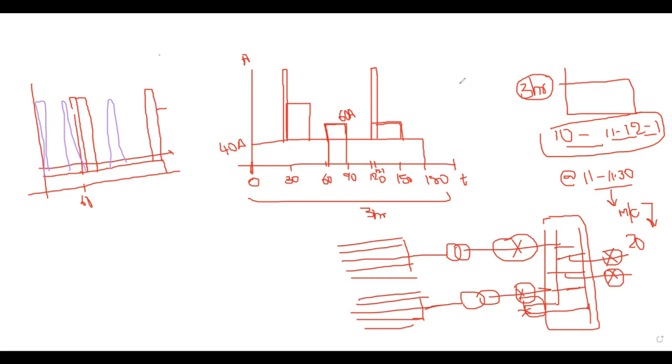A battery is a combination of a number of cells which are connected. So if you are selecting a battery, in that we can find so many cells. So you have to decide the cell voltage. Suppose the cell voltage is 2 volts, then nearly I require 110 cells connected in series. Then the voltage will add up. That gives me a 220 volts battery.